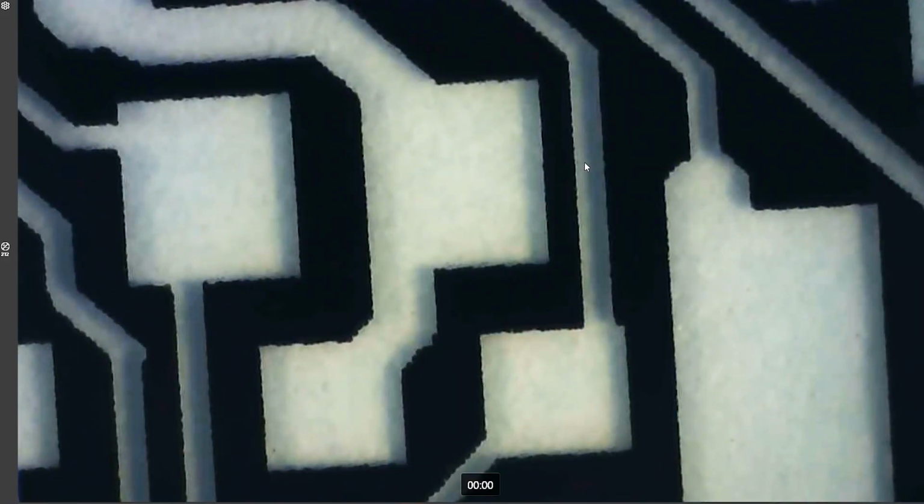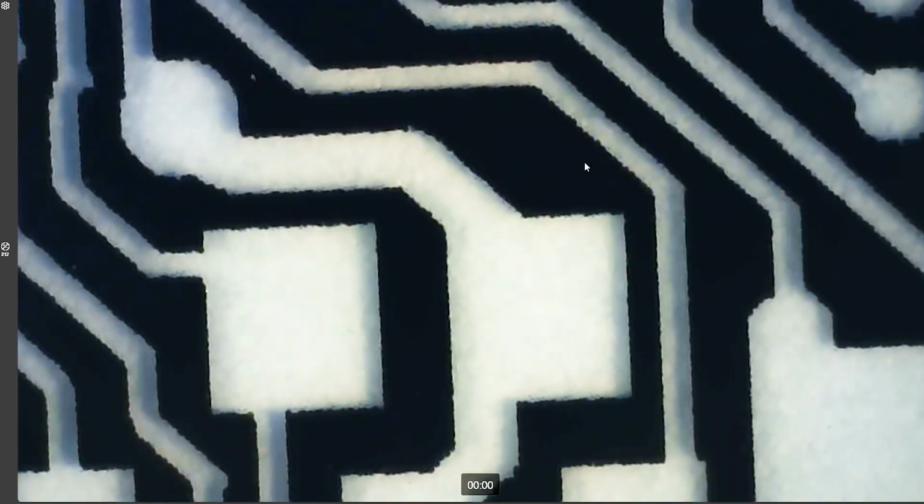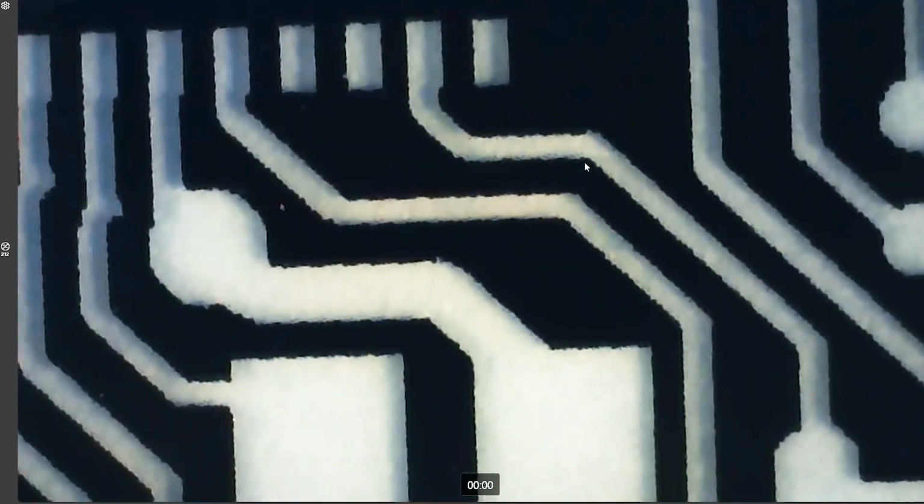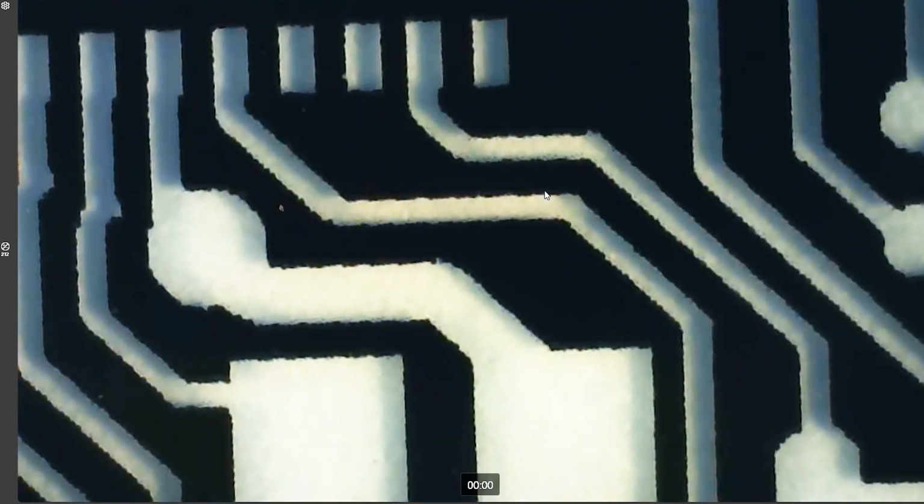And here let's watch from the ink side. Now we're watching from the ink side, and this is why it is important that the ink side should face the photoresist. Here is much better and sharper edges. So you will get the tracks. The tracks will be the same wobbling as here. It's not razor sharp. If you want them razor sharp, at 10 mil tracks, then you need a laser exposure.